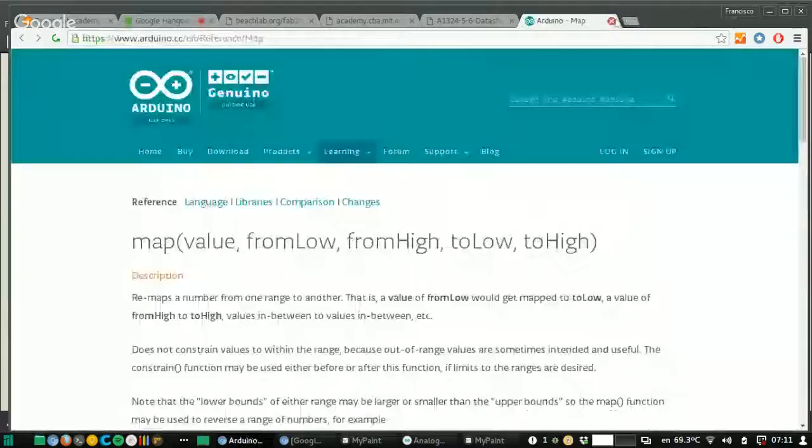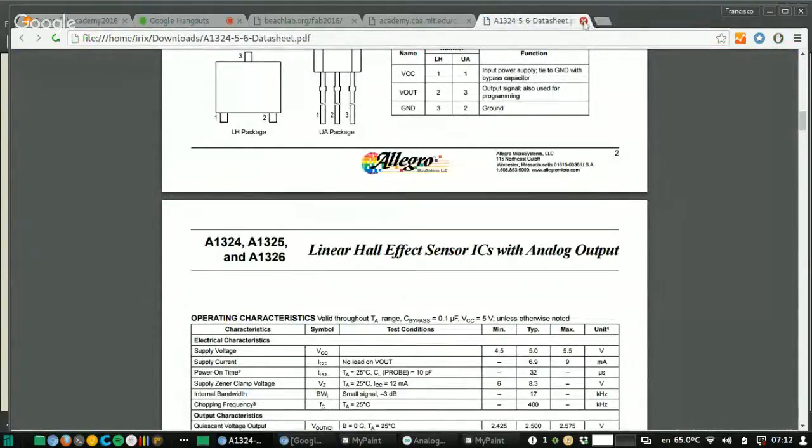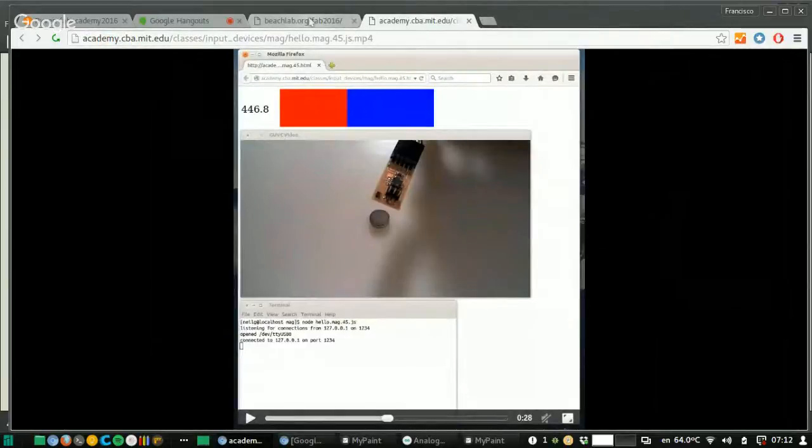Can you talk about the mapping, the pre-scaling? There are different options of pre-scaling. When do you use what? Usually, I saw that in most of the code Neil has, at least for the temperature sensor, he used a pre-scale of 128. That means the clock will be divided by 128 for the ADC. So why does he use that? And if we use a different pre-scaling, what will be the result?